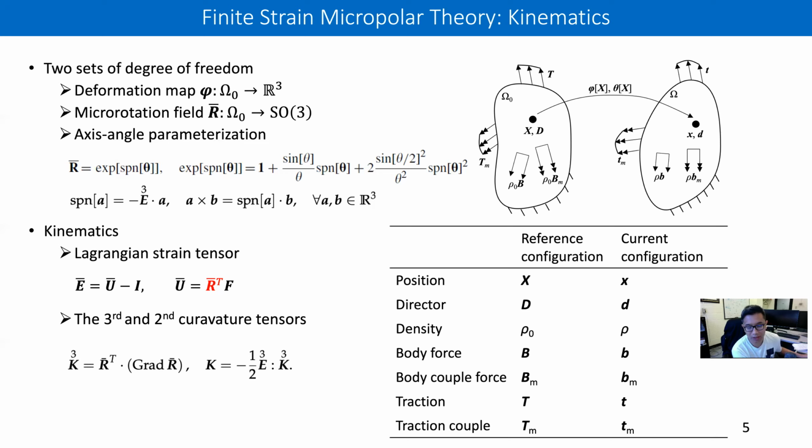So in the large deformation kinematics, it requires specific treatment to actually deal with the evolution law. In this case, we would parameterize it in the axis-angle parameterization. Rotations could be represented by a pseudovector that gives us the spin,